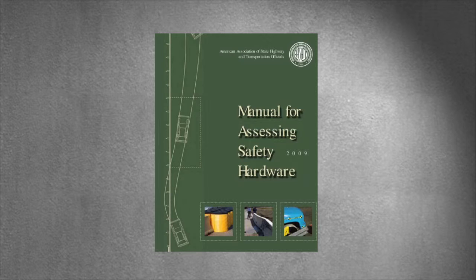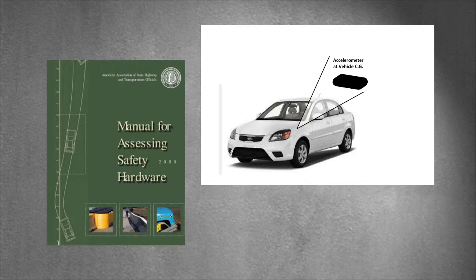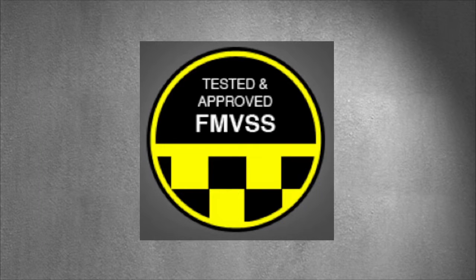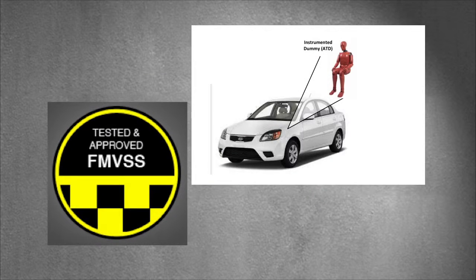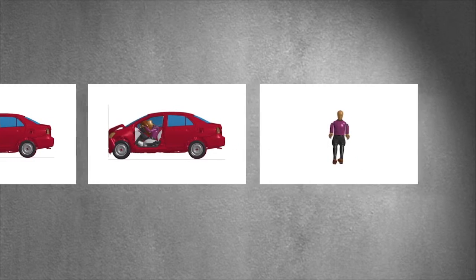In this study, attempts were made to compare real-world occupant injury risk associated with MASH criteria with injury criteria used in the U.S. New Car Assessment Program, also called NCAP. The main objective was to investigate the relationships between the occupant risk determined according to MASH criteria and the ATD injury metrics defined by the US NCAP and the FMVSS standards. In addition, a finite element model was developed and calibrated to nearly replicate the test scenario. The developed model can also be used in future for parametric studies.